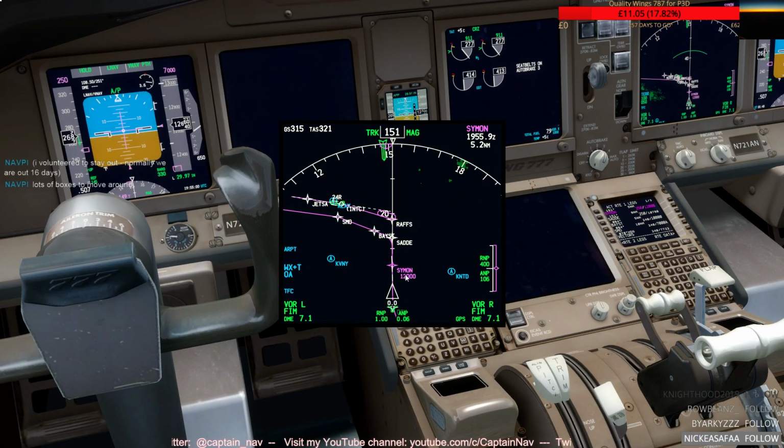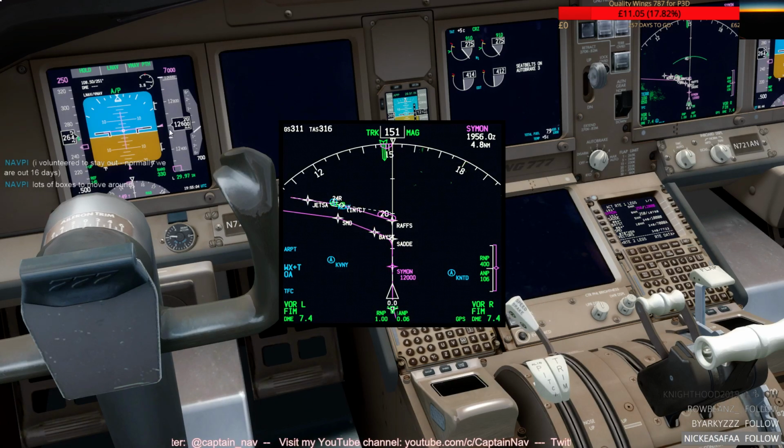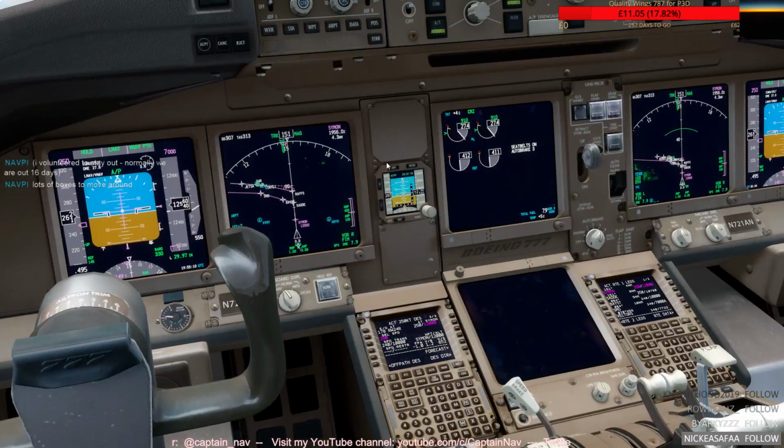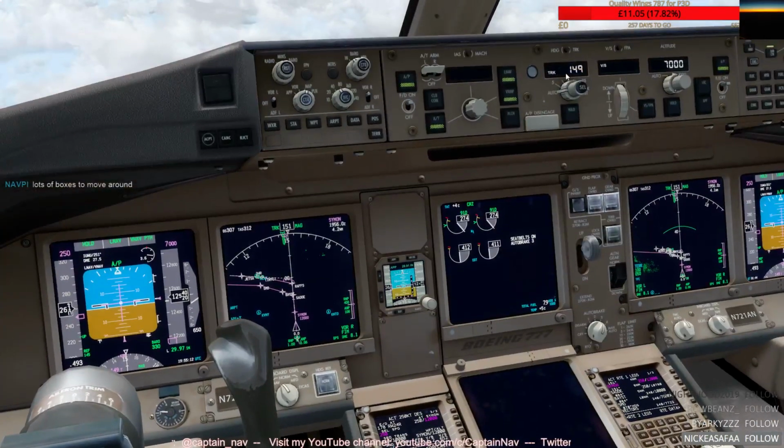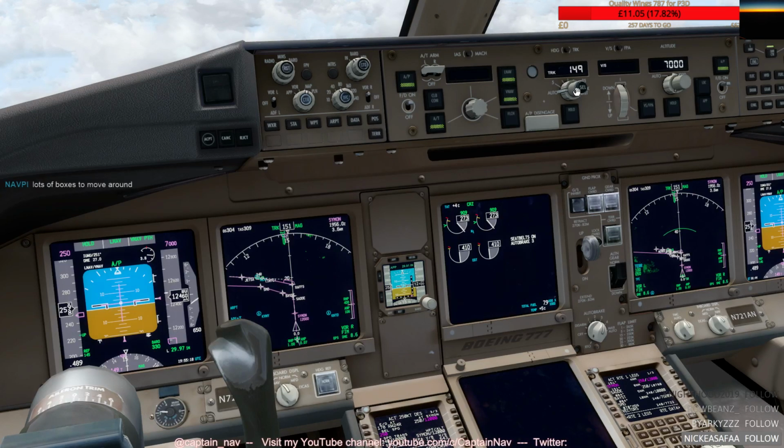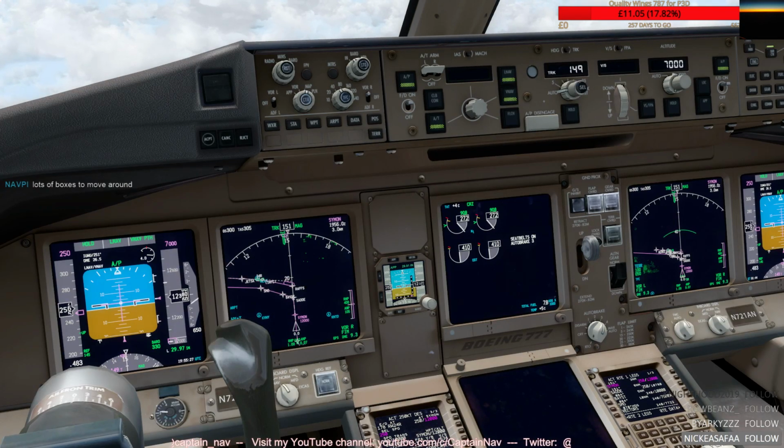It's going to cross Simon there more or less at 12,000 feet. Whereas if you had to calculate that with flight level change or vertical speed, then it will be a nightmare. So that's the plus of VNAV, is that it calculates all the constraints, either speed or level constraints on the arrival, very well.